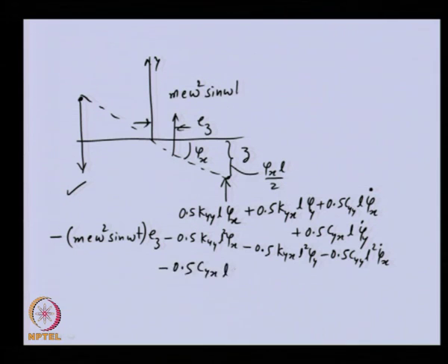So, here we are getting 4 terms from the fluid film forces. Earlier it was only a single term. This should be equal to the diametral mass moment of inertia of the rotor into angular acceleration in the y direction, that is, in this particular plane the tilting is about the x axis. So, this is another equation of motion. On the same line we can write another equation of motion in the other plane, that is in the x z plane.